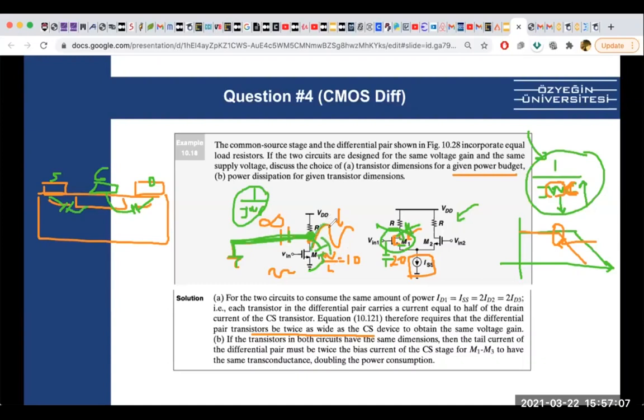So when this VDS cap increases, what happens? The amplitude we want drops a lot, right? Because this cap pulls this voltage to the ground. The current, instead of going to the output, will want to go to the cap.